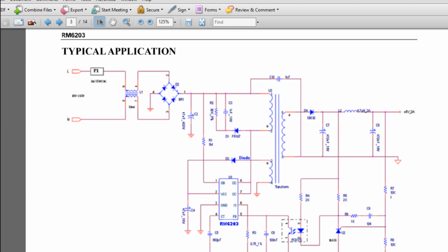And then down at the bottom, it's a thyristor in this case to send signals back to the opto isolator. And you can see that there's an air gap that goes through the opto isolator and up through the transformer and up through that capacitor that keeps the 2 halves of this circuit separate.